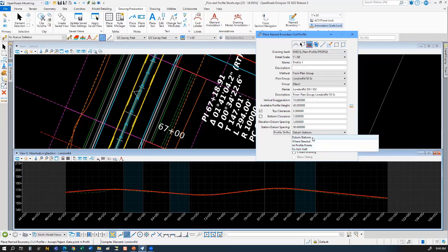All right, now if you set it to datum stage, what it's going to look at is these two values here. It's going to shift it up and down in multiples of 5 feet for the elevation, and it's going to lock it into breaking at, in this case, a 50-foot interval. So at every even foot 50. So 10 plus 50, 11, 11 plus 50, that type of situation. Or you can change this to every 100 feet or what have you, whatever you want.